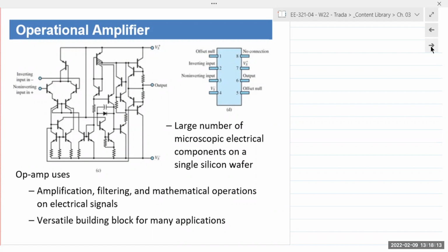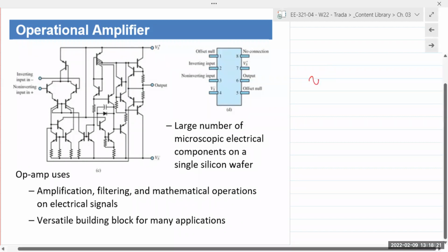All right. Now, again, remember from the BJT chapter and the topic of amplification, you can give a small AC signal, and the power to amplify this comes from the DC power supply. So small AC plus large DC gives you a large AC signal.